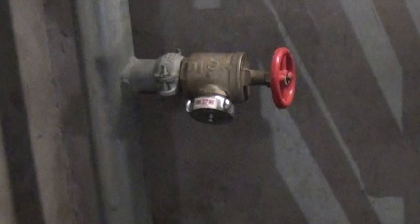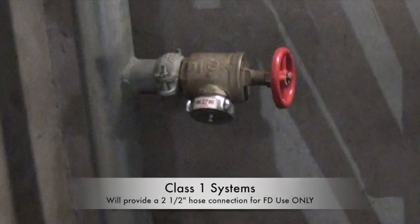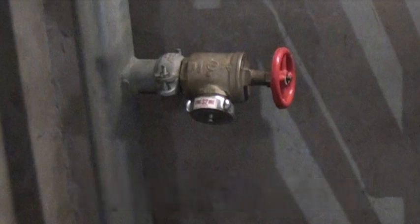Class 1 systems. These will provide a 2.5-inch hose connection for use by the fire department only. These systems, as a whole, will supply at least 500 gallons per minute at the uppermost floor of the structure.